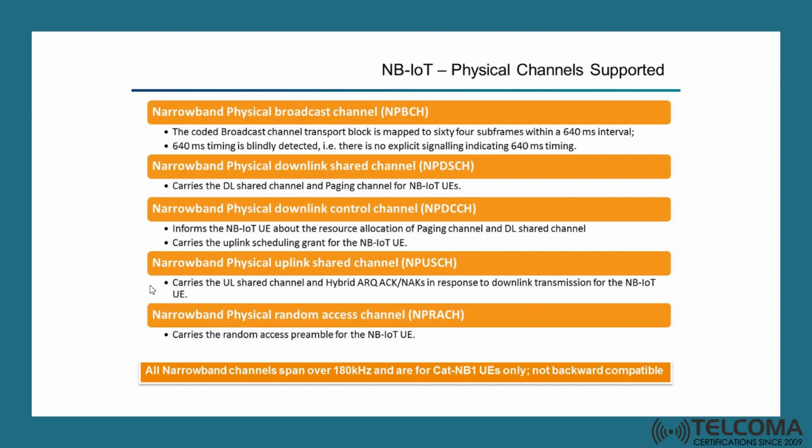So all the channels have to be newly introduced for this 180 kilohertz spectrum. All these channels such as PBCH, PDSCH, PDCCH, PUSCH, PRACH are redefined. The difference is they have added a prefix of N, and now the PBCH channel has become the NPBCH channel.